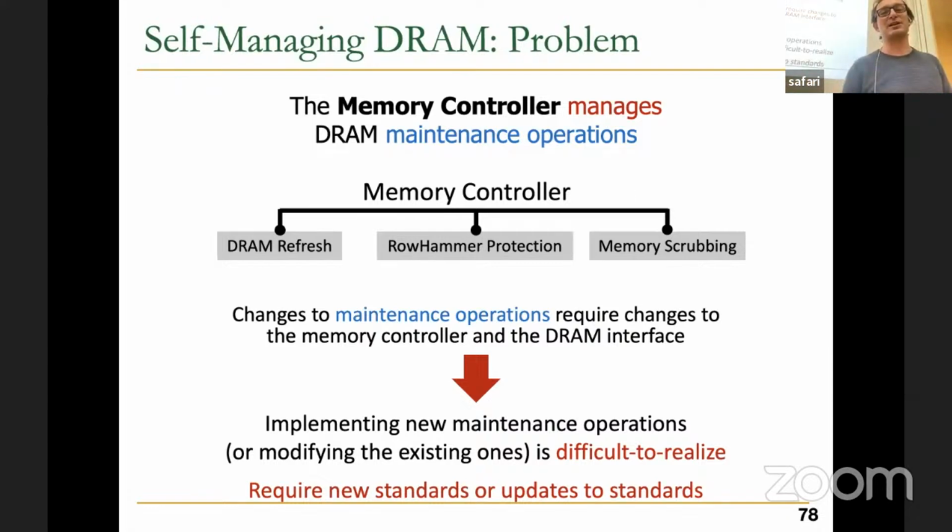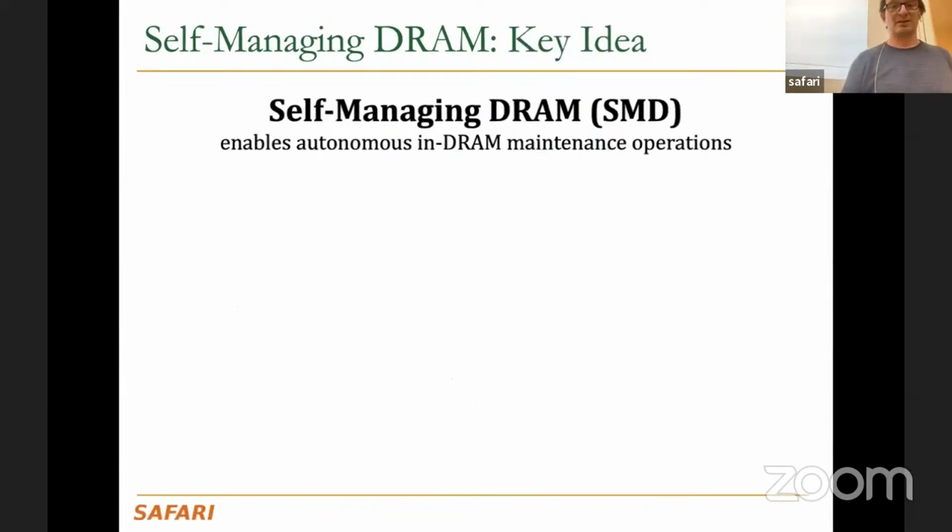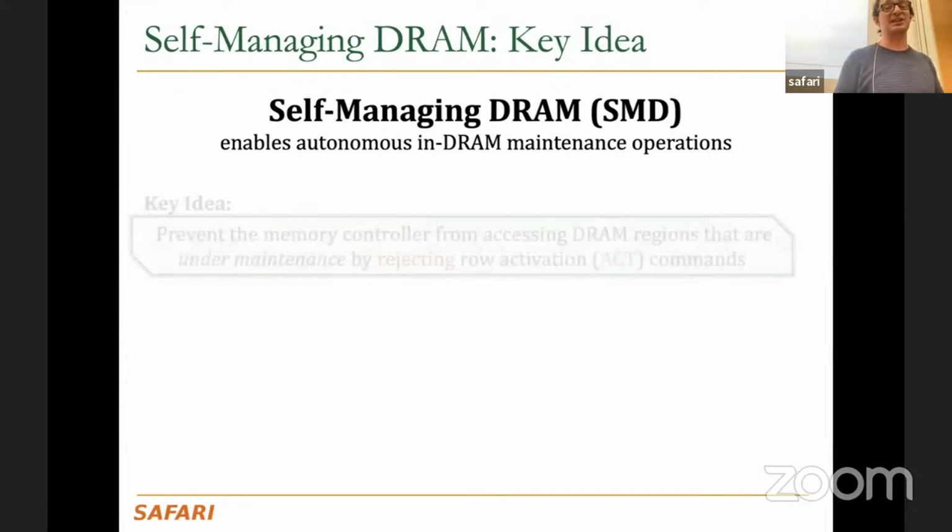And the idea in this work is to basically decouple the concerns, right? Have a better interface such that some things can be done internally in the DRAM, especially those things that the DRAM manufacturer can do much better alone themselves. And some other things are done in the memory controller, and they don't necessarily get exposed to memory. And the memory controller doesn't need to tell the DRAM to refresh at this time, right? So this is the idea of self-managing DRAM to enable more autonomous and efficient DRAM operations.